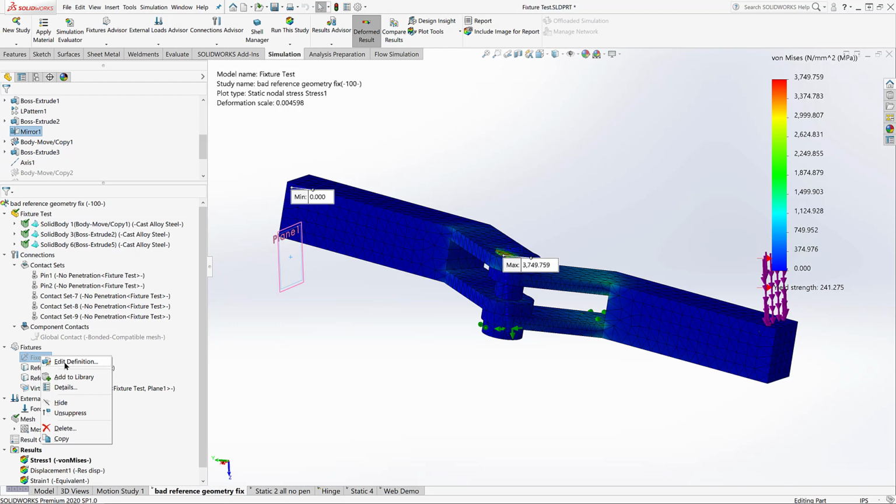So that's something to keep in mind. If you are using a virtual wall, you really want to make sure that you have your constraints set in place so that you're not going to push your part outside of where it's supposed to be. Or if you know that the part isn't working with abhorrently large forces, then you could safely give it a fixed geometry fixture. And that would take care of it.